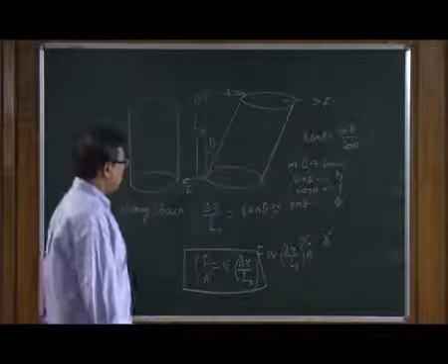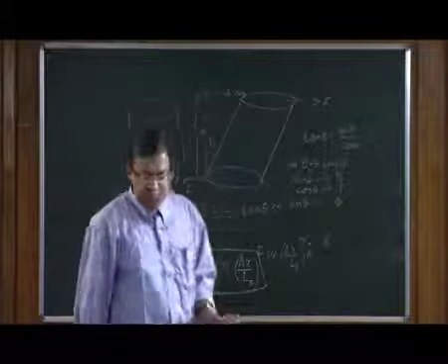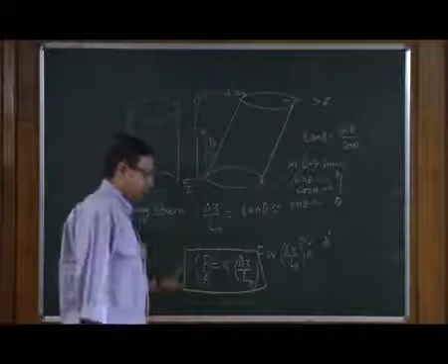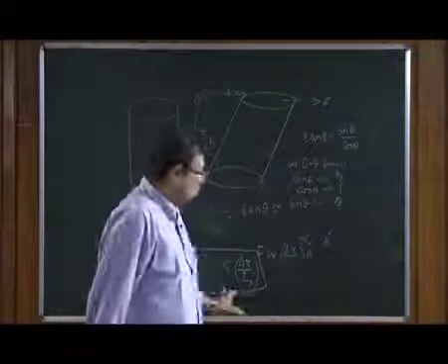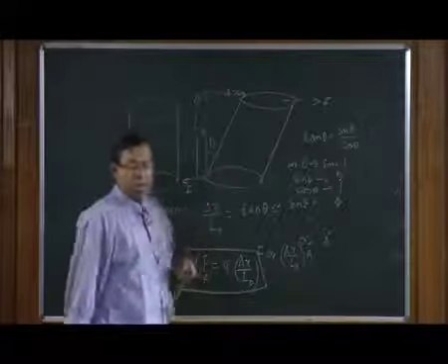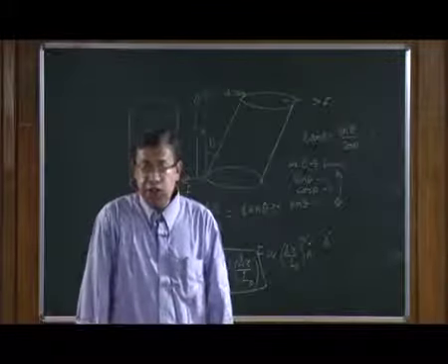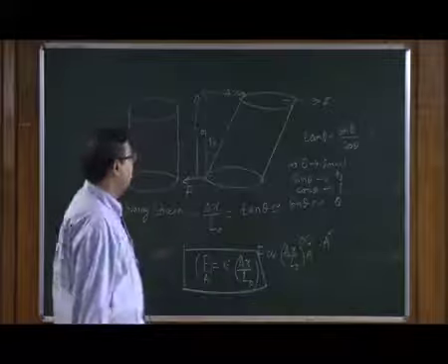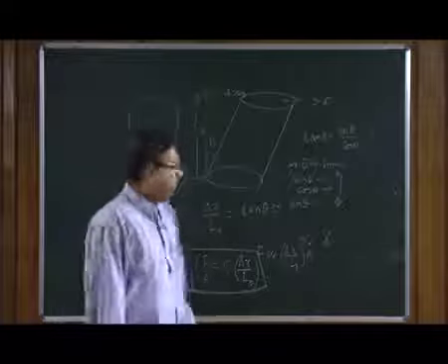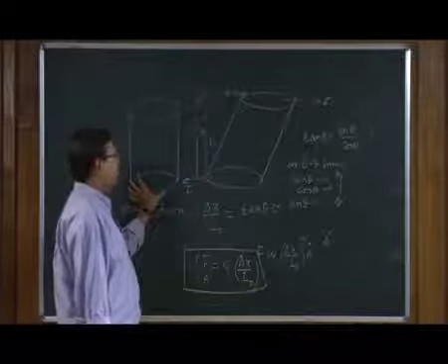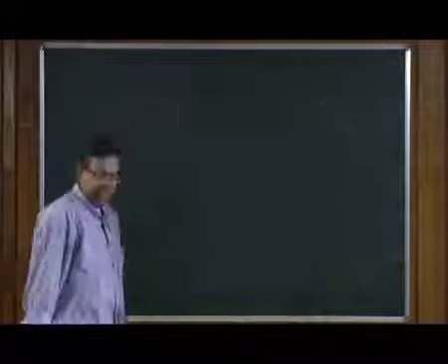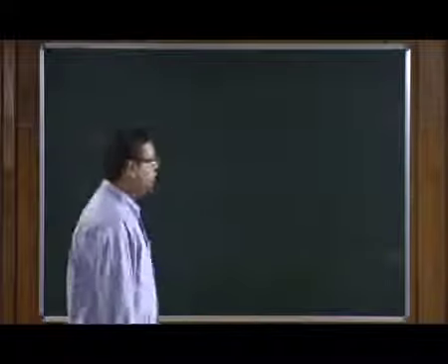So, these are the shearing stress and the shearing strain relation, and this is very similar not only in the looks, but also in form, excepting that you have not caused any extension or compression, but have simply applied a shearing force, because of which this upright cylinder has become a cylinder which is inclined at an angle theta. So, the next thing that we are going to talk about is volume deformation.